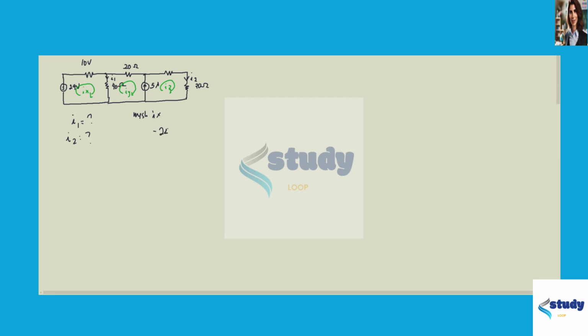negative 24 plus 10 Ix plus 40 times Ix minus Iy equals 0. So this is just the KVL across mesh Ix. Now, we could write a super mesh that goes from the second and the third loops here. We could label it in red here for the super mesh.